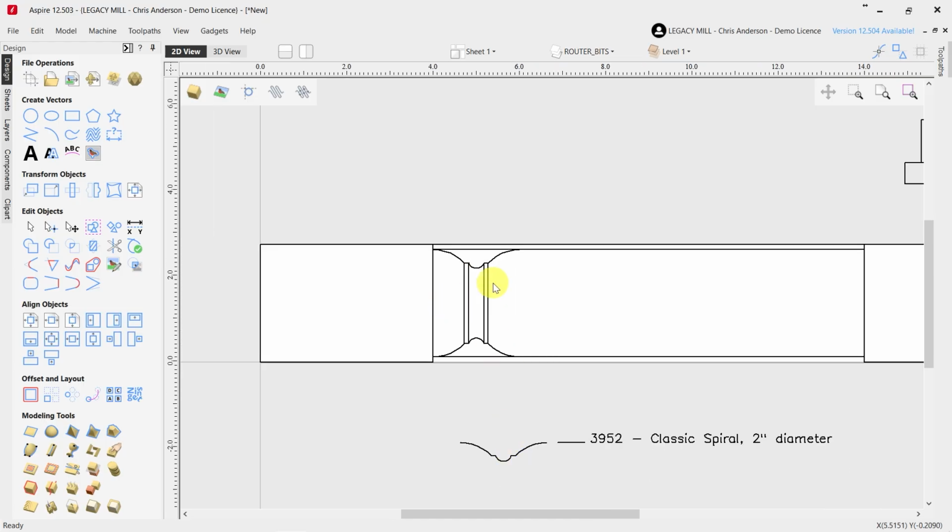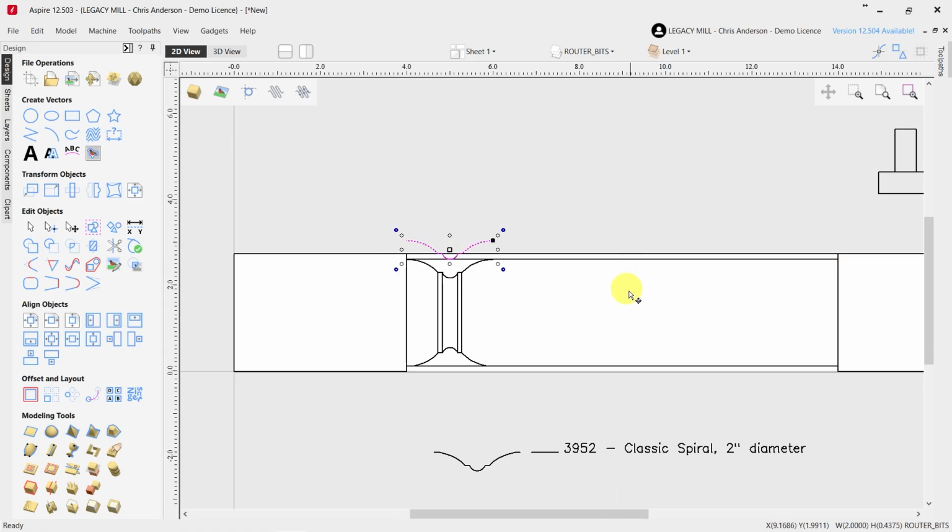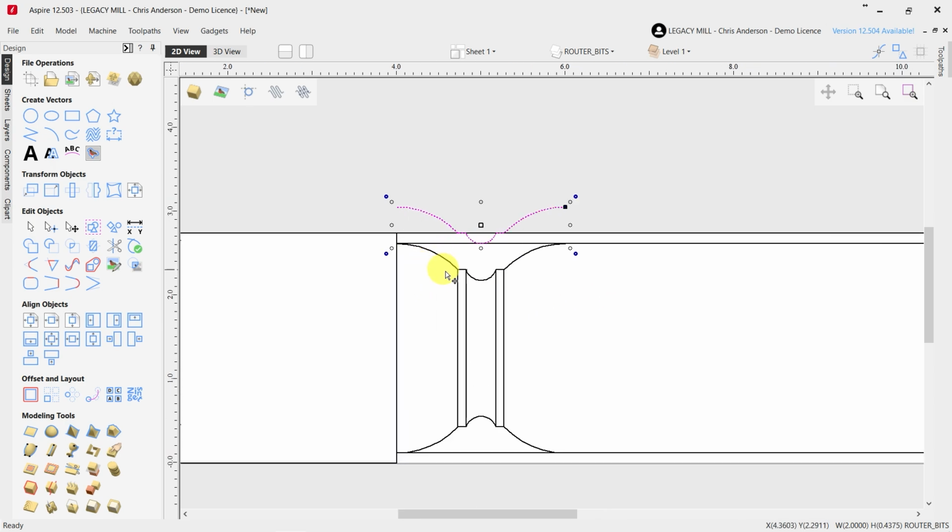So how is the cutter actually going to give us that result? Well, let's explain the toolpath. The cutter is going to take the tip of the cutter and position over where we want it to cut, let's say the x-axis. It's going to lower the cutter down to get to a starting surface. So this has already been turned round to 2.5 inches from our previous video. And so the cutter is going to start from that surface, and then it's going to move down at a controlled speed, as the stock is rotating, until it gets to the final cut position.